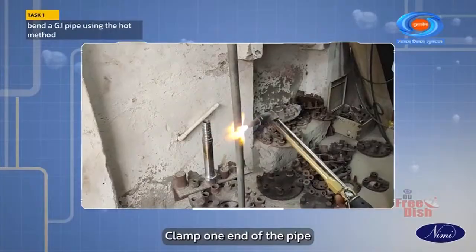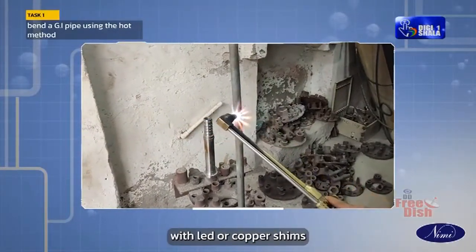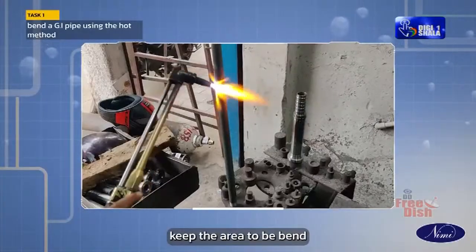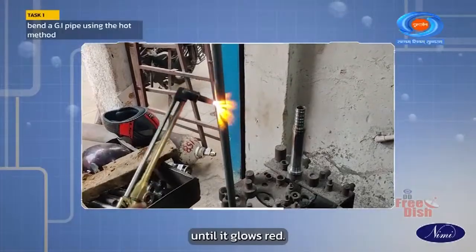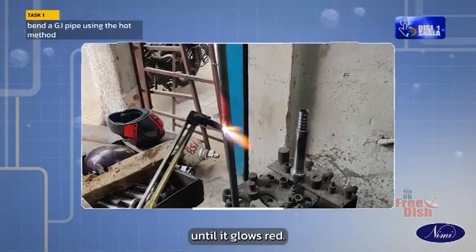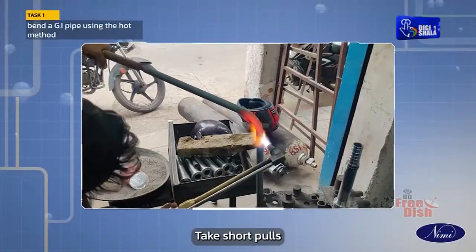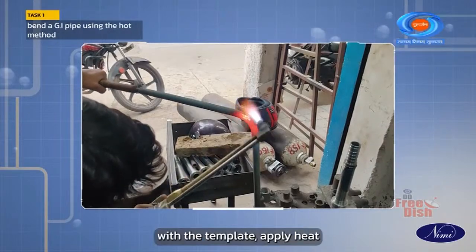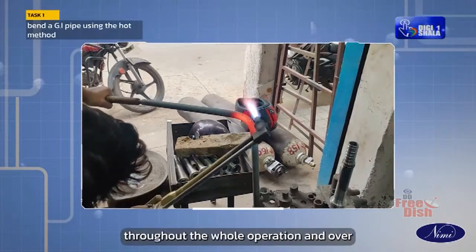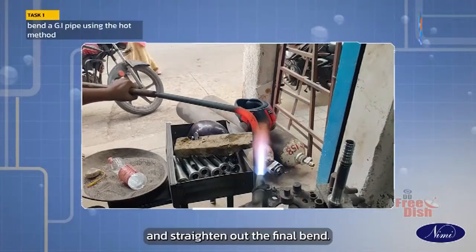Clamp one end of the pipe in a vise and protect the clamped portion of the pipe with lead or copper shims. Heat the area to be bent using an oxyacetylene torch until it glows red. Pull down the pipe gently in the direction of the bend. Take short pulls until the correct bend angle is reached. Check the bend radius with a template. Apply heat throughout the whole operation and overbend slightly and straighten out the final bend.